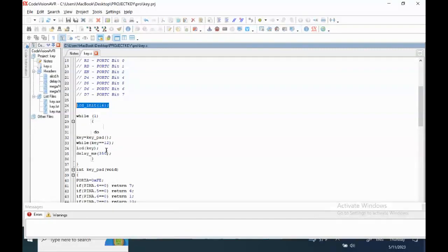Then inside the while(1) function, we merged two user-defined functions, one of them related to scanning of the keypad, and the other one printing the scanned values on LCD. And we wanted our microcontroller to do nothing when no key is pressed, and to do that I use a key which does not exist in my key numbers in scanning values. For example, you can change it to any number that you desire, 50, for example.